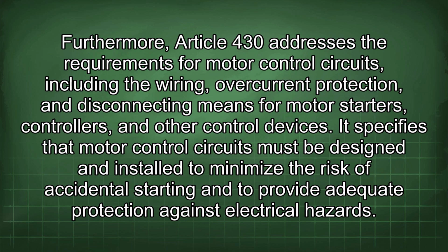Furthermore, Article 430 addresses the requirements for motor control circuits, including the wiring, overcurrent protection, and disconnecting means for motor starters, controllers, and other control devices. It specifies that motor control circuits must be designed and installed to minimize the risk of accidental starting and to provide adequate protection against electrical hazards.